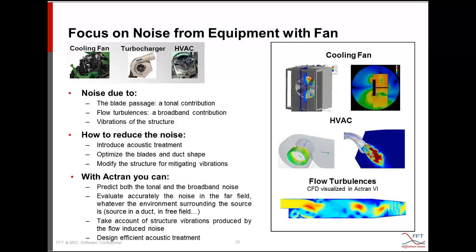So we have already addressed the noise coming from the powertrain, the intake and the exhaust. Now I'm going to talk about equipment with fan. Equipment with fan, like cooling fans or HVAC, also makes a lot of noise. The fan noise is far more important for a tractor or an excavator than for a car, because engines are bigger, first, and then vehicles are slow or stationary. So the airspeed is very low, and the fan has a more important role for cooling the engine, and is thus bigger and produces more noise.